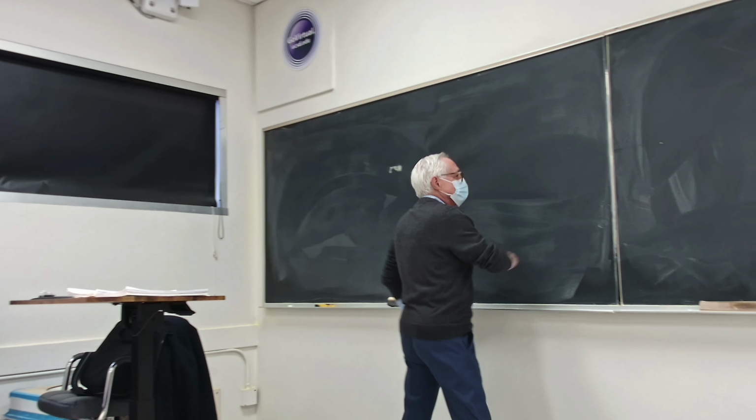the W dot of the control volume, right? Plus summation over all inlets, m dot i, and therefore h_i, V_i squared over 2 if there is any significant velocities. Because usually these terms are much smaller than this one, than h.